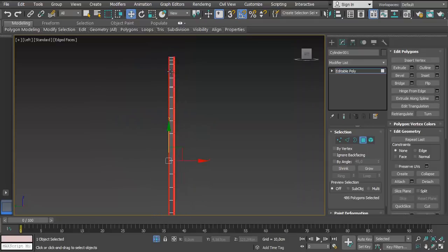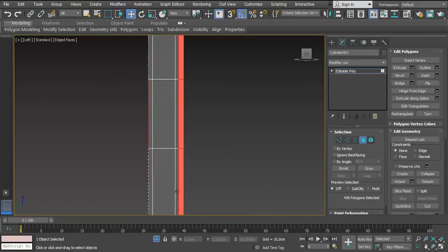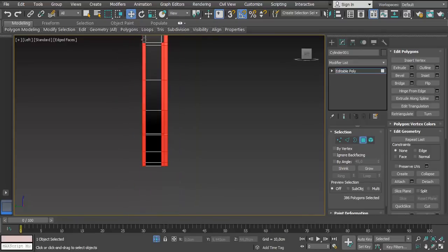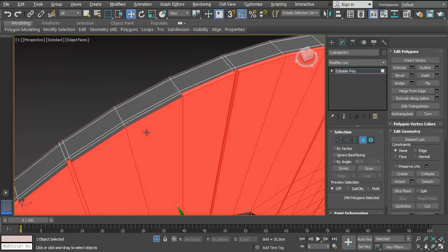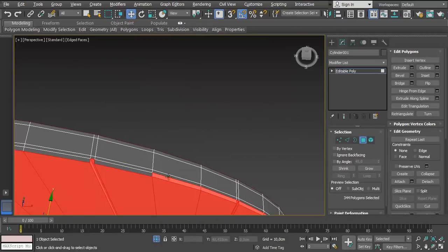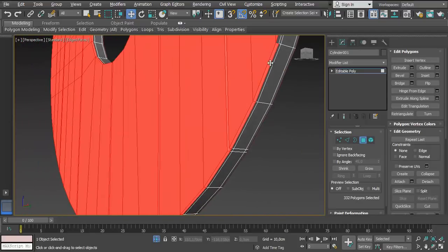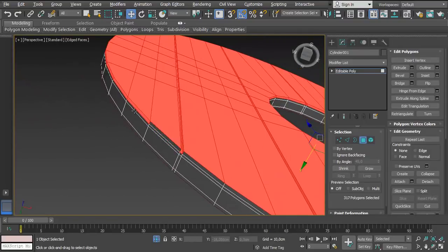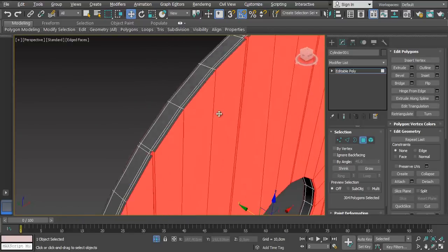And as you can see here, I am trying to select a certain area, because in order to do supporting edges when it comes to cylindrical stuff, especially when the cylinder is not perfect, which means there are a lot of edges right there, using edge selection is not going to allow us to select perfectly. So the only option we have is to go manually and select only the surface we need, which covers the circle we are concerned about in order to do supporting edges.